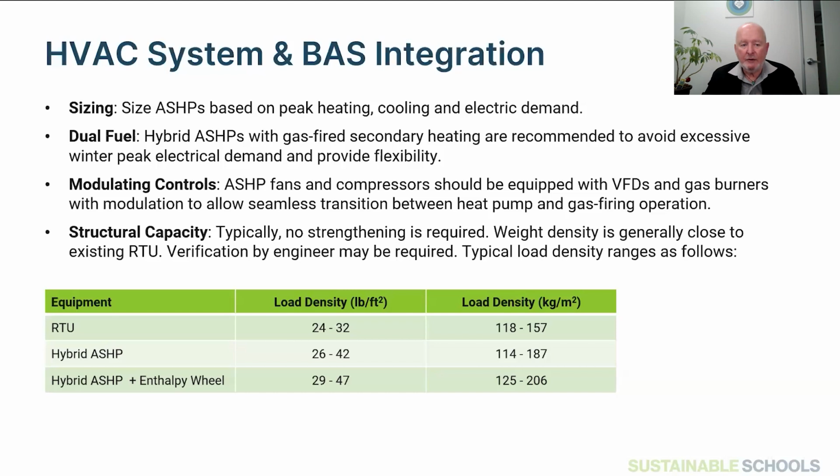Again, the dual fuel, we believe that hybrid is here to stay for the coming years and is the right approach to take. Modulating controls, this ability to control smoothly between air source heat pump operation and gas operation without them fighting each other, overlapping. And typically, we're not finding a lot of issues with rooftop unit applications around structural capacity of the buildings to take them. But these are all considerations you should be discussing with your design team as these projects proceed. Next slide, please.